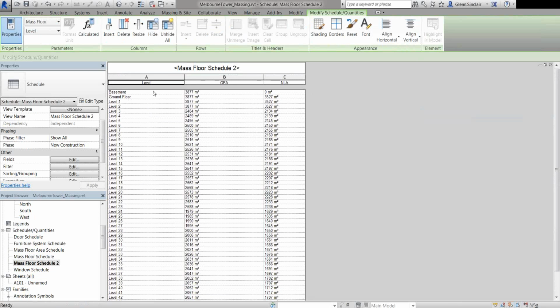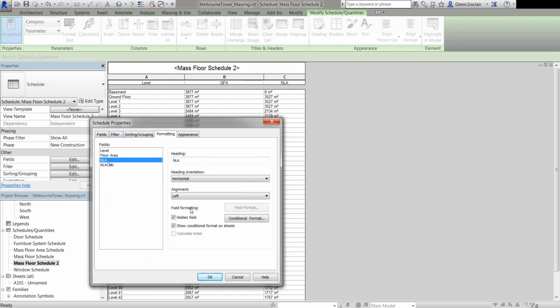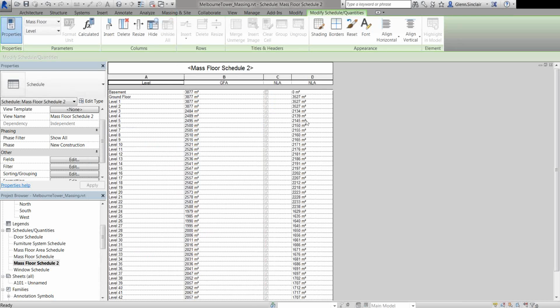So there we go, we chose basement was unticked, NLA was unticked. To see that, I can show again the NLA tick box field in my schedule here. If I untick it for ground floor as well as all not lettable, then the NLA count turns over to 0.